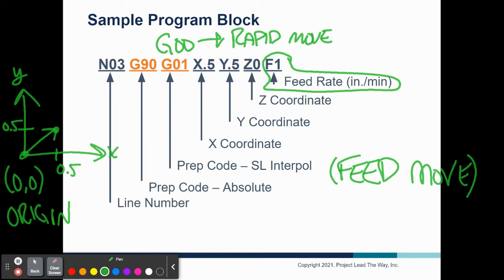So when you do more complex machining, like an airfoil of a, yeah, Michael. So why would you not want to use rapid? In this case, say that this material, you're actually cutting this line, right? So we're trying to go from here to here, and we're trying to cut something. That's when you don't want to use a rapid move, because with a rapid move you can't actually control how fast it's going. It's just going to go as fast as it can.